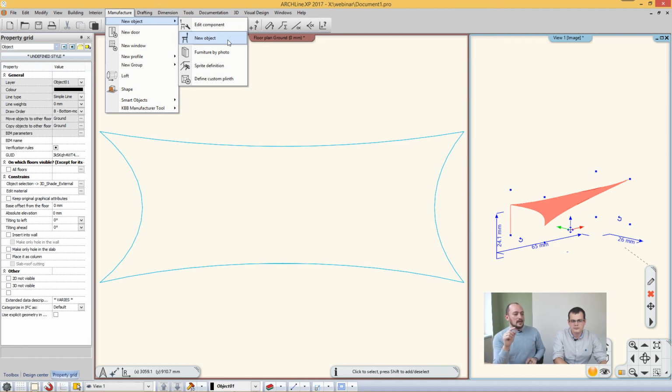The reason I usually suggest this to our users is that if you import something into a living project and it has hidden parts which are falling into walls or something that you cannot see, then you can easily fill up your project with trash that you won't be able to see and won't be able to get rid of, and it just makes your project larger and larger. So thank you for mentioning that one, as it is the proper way of importing things and deciding what to do with them.